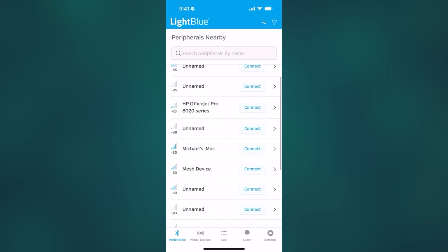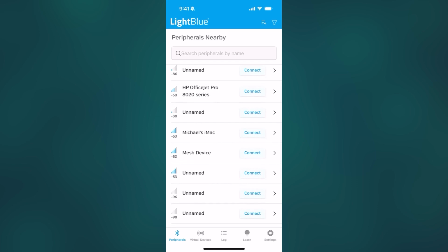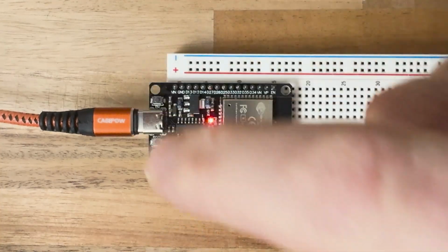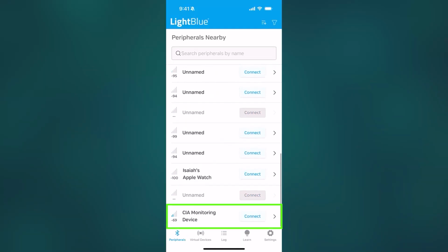What happens when your device gets connected to and then disconnected is that the advertising that we started automatically stops. As soon as a client connects, that is when the advertising stops. So if we want to continue to advertise to other devices out there, or to advertise again after one of the devices disconnects, we need to start the advertising again. Just to show you, I'm going to go ahead and reset. I just reset my ESP32, and now see how we see it down here at the bottom again. I'll just go through this one more time.